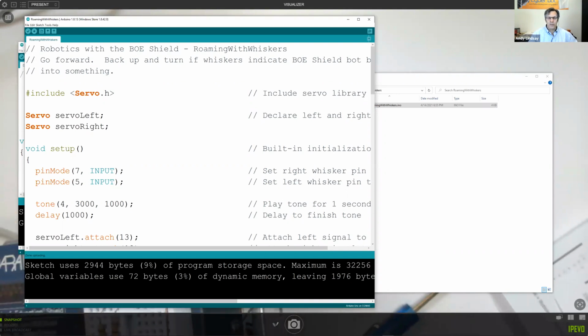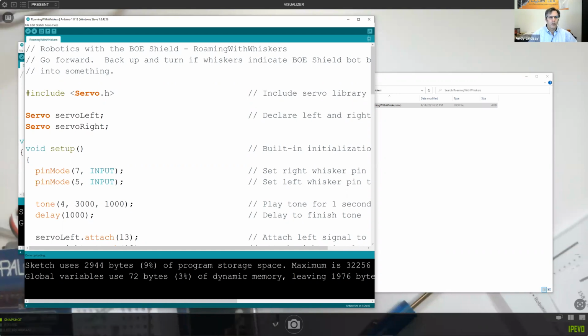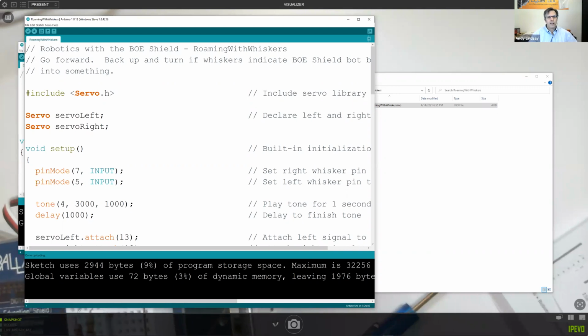When the battery voltage tanks, because it has to supply a bunch of energy to the servos to force a change in direction, the Arduino shuts down. When it wakes back up, it starts over at the beginning of the program, making a speaker beep.